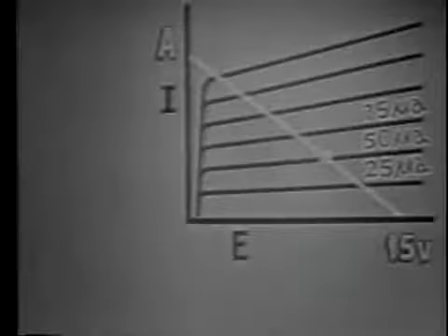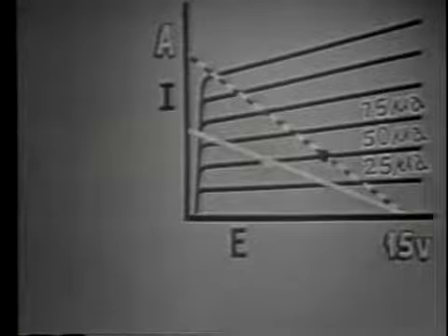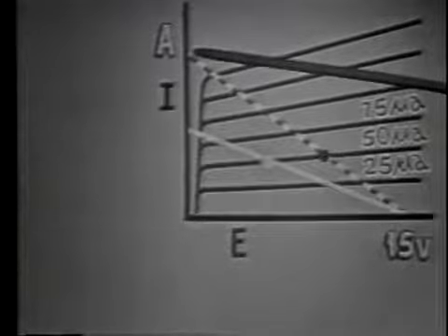Having constructed and used the load line to discuss how the circuit amplifies, let's change the size of the collector load resistor and notice what happens to the load line. We will also see what happens to gain while changing the load resistor. Keeping the same VCC and input signal and using the load line we just drew for reference, we will change only the load resistor.